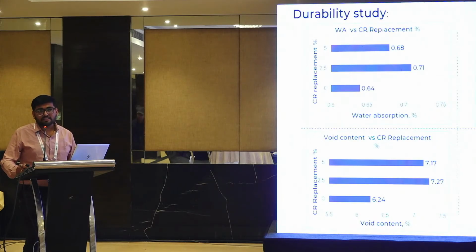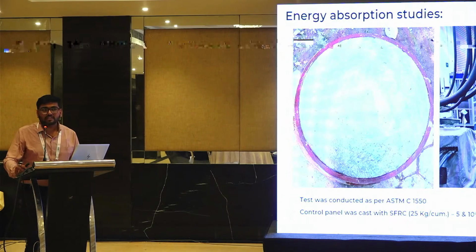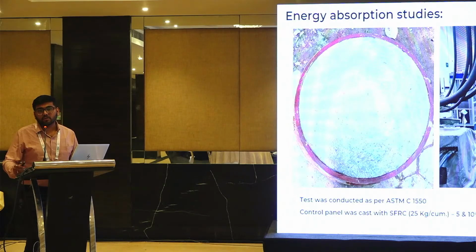The only thing is, the mix will be inferior in water permeation, because the rubber particles are to penetrate at a higher pressure. But our major interest is to use the crumb rubber for improving the structural characteristics of the concrete. So we are studying how the rubber incorporation will affect the energy absorption of the concrete mixes or the damping ratio.